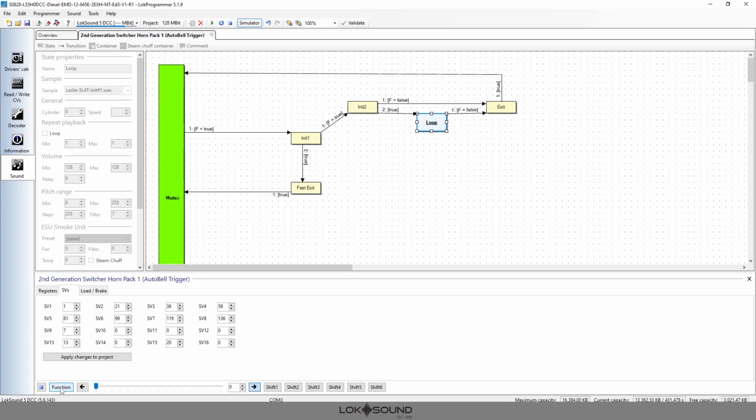If I just press function very quickly and turn it back off, it's looking here. It's looking to see if the button is still on. It's going to continue on. If it's not still on, it's going to come out. So in my case here, I pressed it so fast it never went to the initial 2. It came right out. Very short blast on the horn.